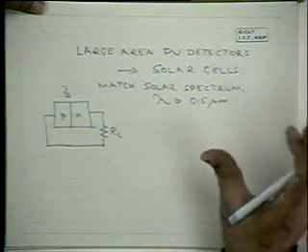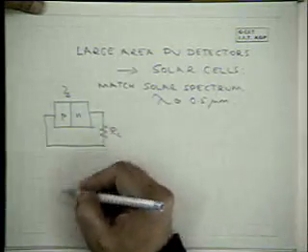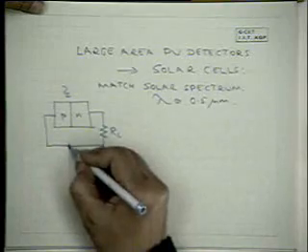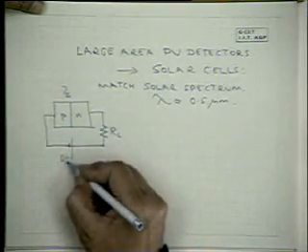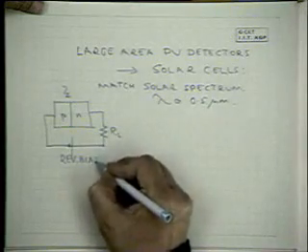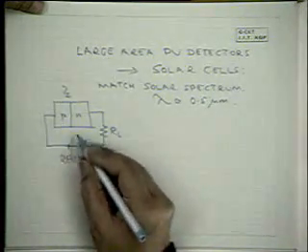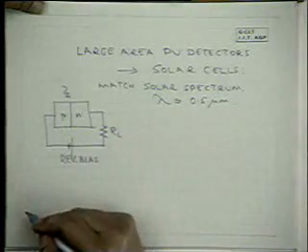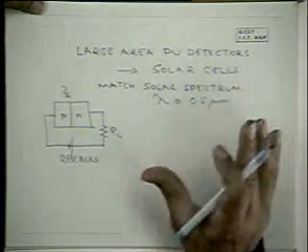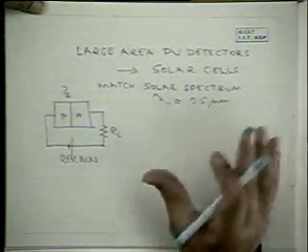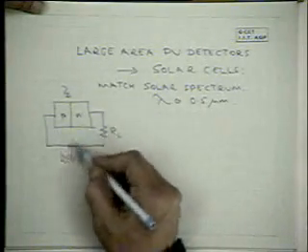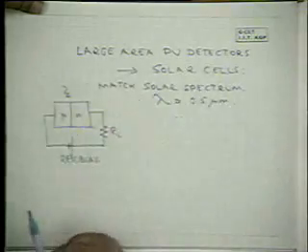But let me mention that in the case of photodetectors which are used in the infrared, often you do use a reverse bias, often in order to get higher speed. In APDs, obviously there is a high voltage applied. But whereas for a photoconductor it is absolutely essential to have a bias, in this case you need not have a bias because the junction itself separates the charge carriers.